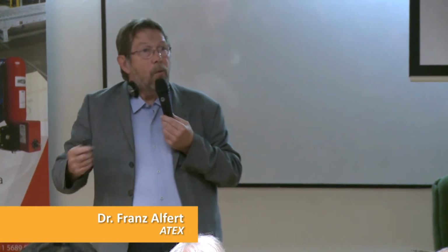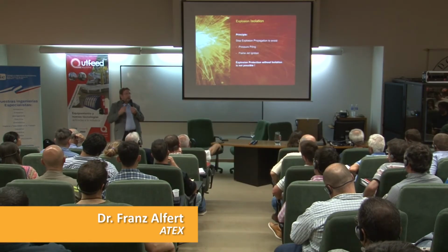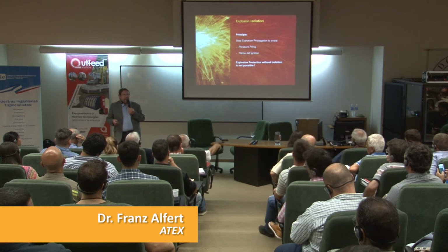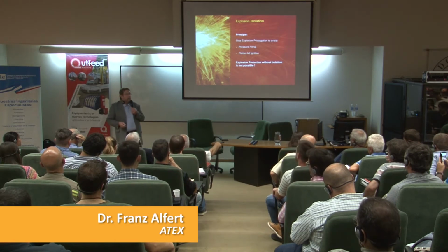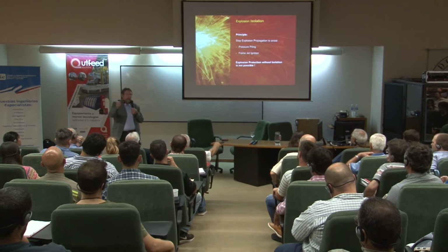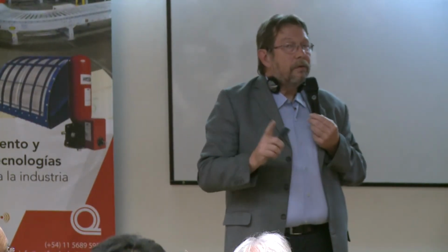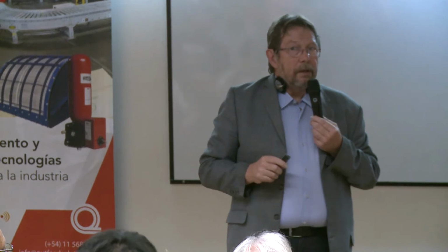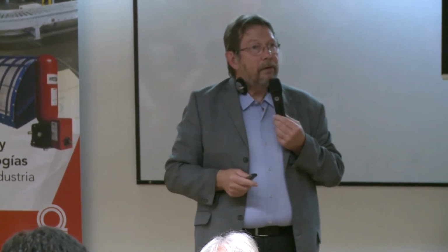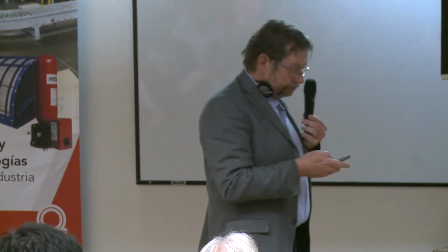So if you have one main elevator that is the only one that can take product or distribute product, or a distributor somewhere that is feeding into many different silos, those are the things one looks at in order to keep the plant running. But as I say, explosion isolation first, the most important thing.